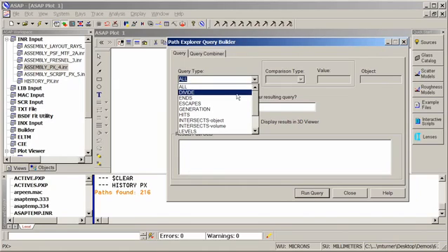For instance, I can go through and look for those rays that divide at a particular surface or object within ASAP. Similarly, I can look for rays that end on particular objects or rays that escape the system. These would be rays that did not end on an absorbing surface. I can sort the rays by their generation. The 0th generation are the first rays that come from the original source, and then each level of splitting and/or scattering will create a subsequent generation.